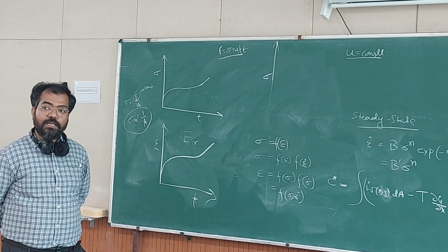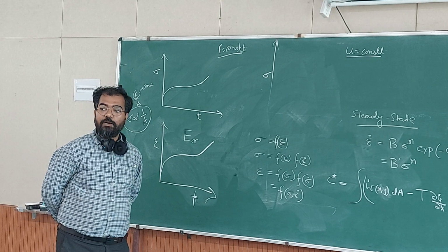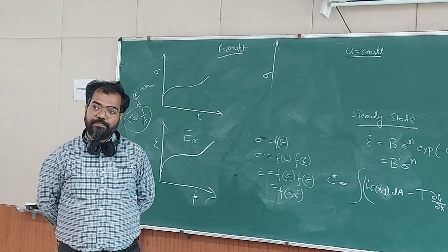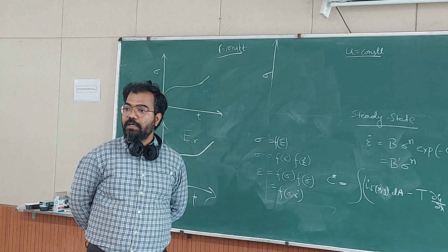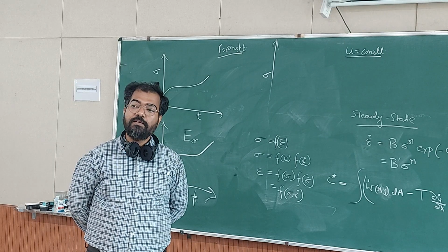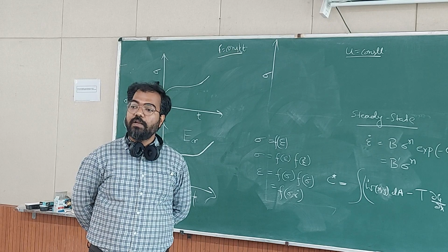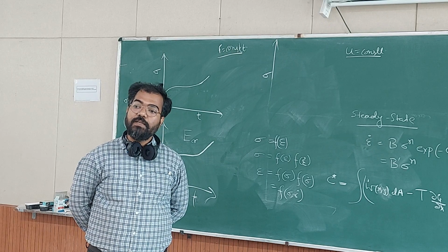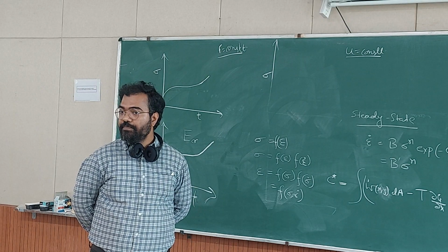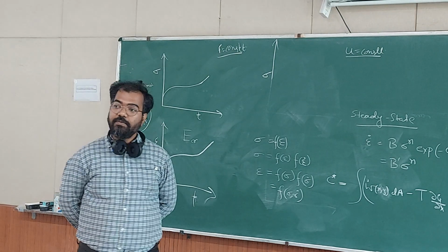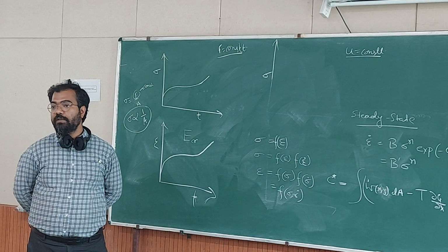but the idea originated, K was not derived to calculate how much stress is getting intensified. K was not derived with that objective. K was a byproduct when what are the stresses in presence of a crack according to theory of elasticity was being derived by various researchers. Okay, so there was a factor which was common when you describe sigma xx, sigma yy, sigma xy.